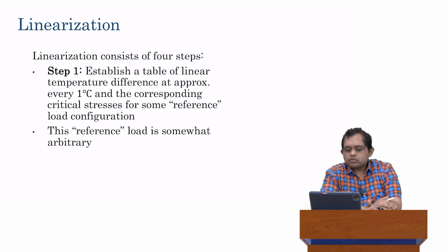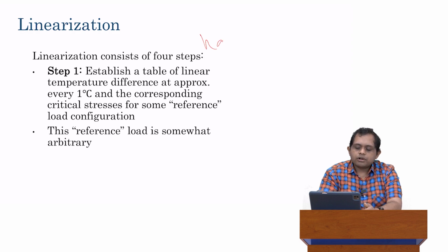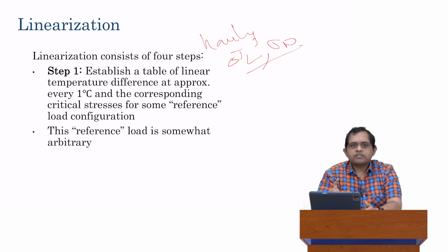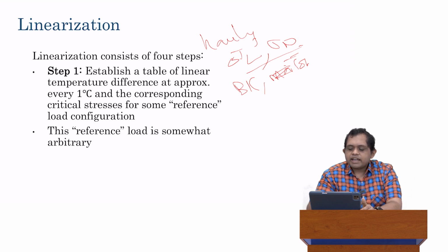Let's go through the process of this linearization, or thermal linearization. What you want to remember is that before we do linearization, we have two things. At every hour, we have this delta TL, which we've calculated, and we also have the eigenstresses. We have calculated both of these at every hour. Separately, keep in mind, we also still have built-in curling and moisture effects, so let me just write that as TSH. We also have these effects to think about. We also have some knowledge of traffic, which is our axle load distribution as well as our axle configuration.